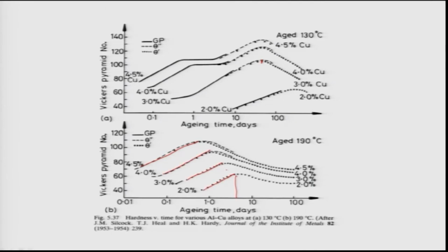So, if the heat treatment is done in such a way that the temperature and time are selected properly, then the hardness can be made to fall on the increasing side of these hardness plots, and then we can achieve a good combination of strength and ductility. That is what is actually done. So, the selection of heat treatment temperature and time has to be judiciously done, otherwise alloys will not be applicable in real applications. That is a very important aspect which you must remember.